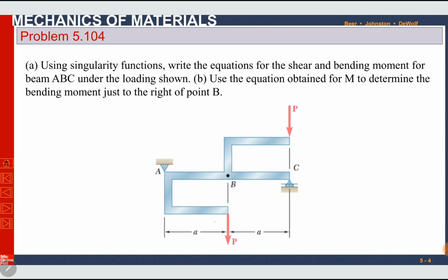First, in this beam, we have to shift this point force P from here to point A. So it will be P, but by shifting a force from its point of application, offset of its line of application, it has to be replaced with a force and a couple system.